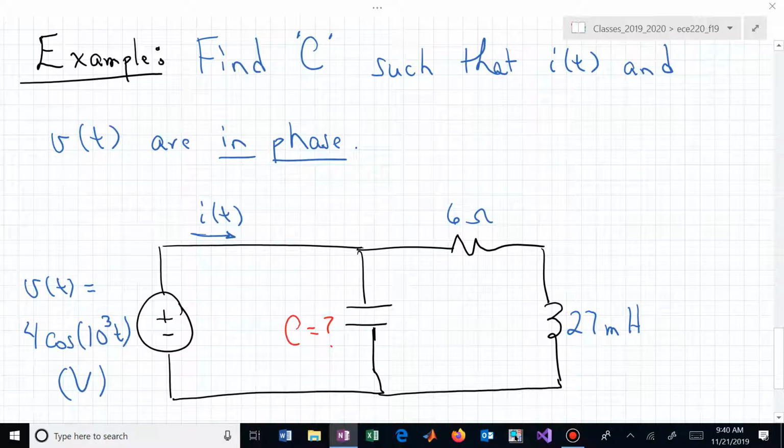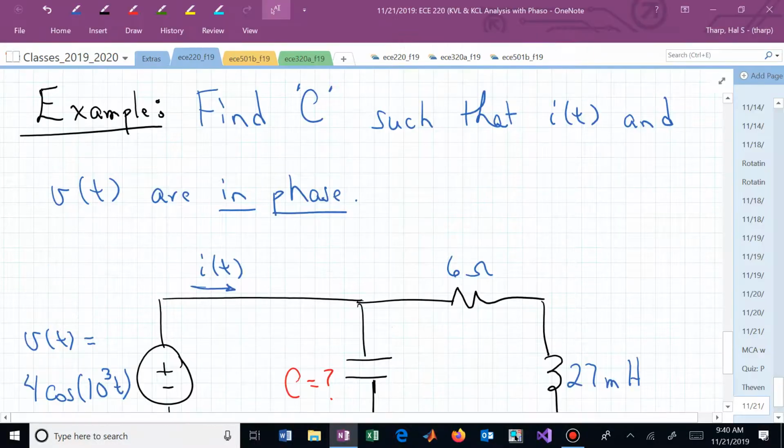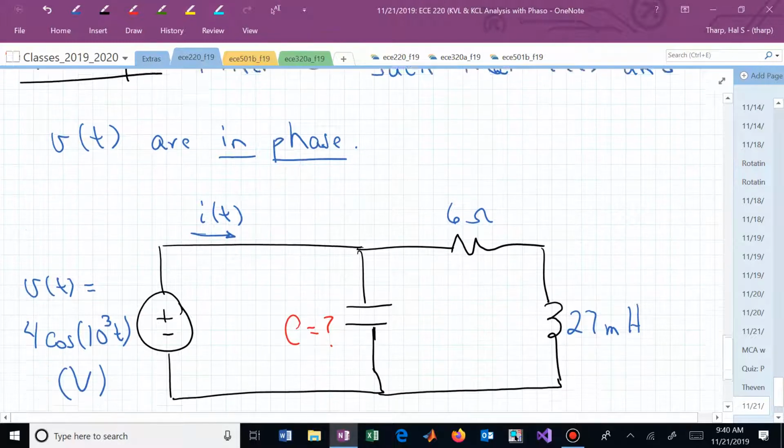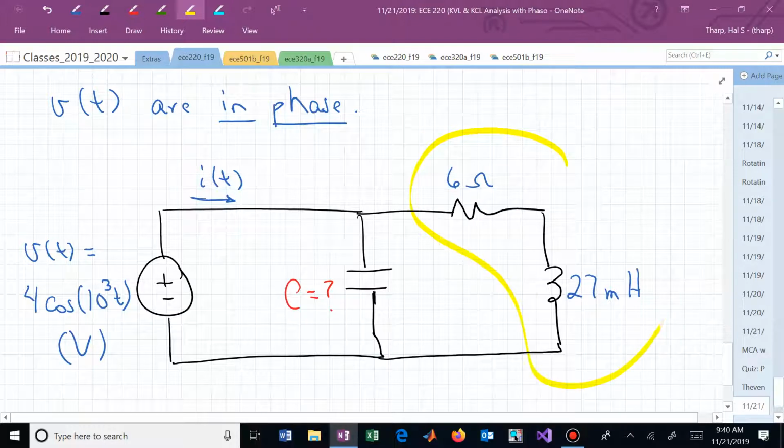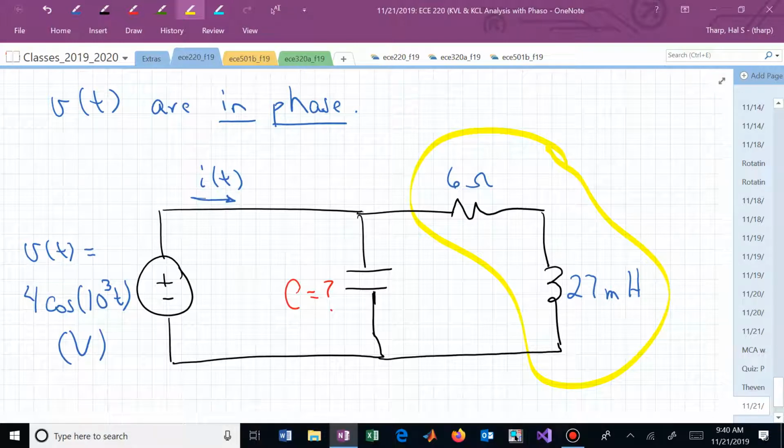What you can be thinking of while you're sketching this is you could be trying to connect this with a real system, and you might say, oh, you know what, this is really how I'm modeling the impedance that my motor is presenting to the power company. I have this huge motor, and to the power company it looks like 6 ohms in series with 27 millihenries because of all the wire in the coils and the wrappings. So now you have 6 plus j27m,